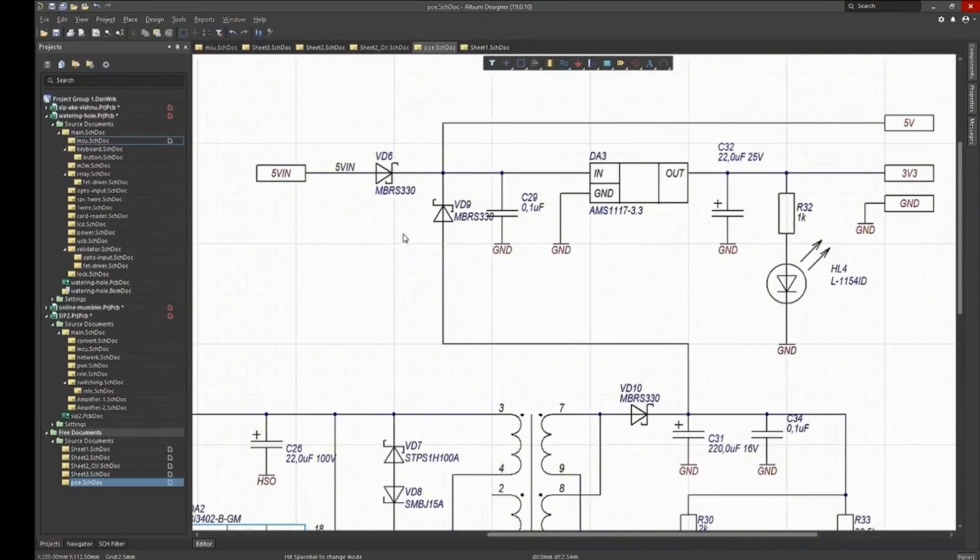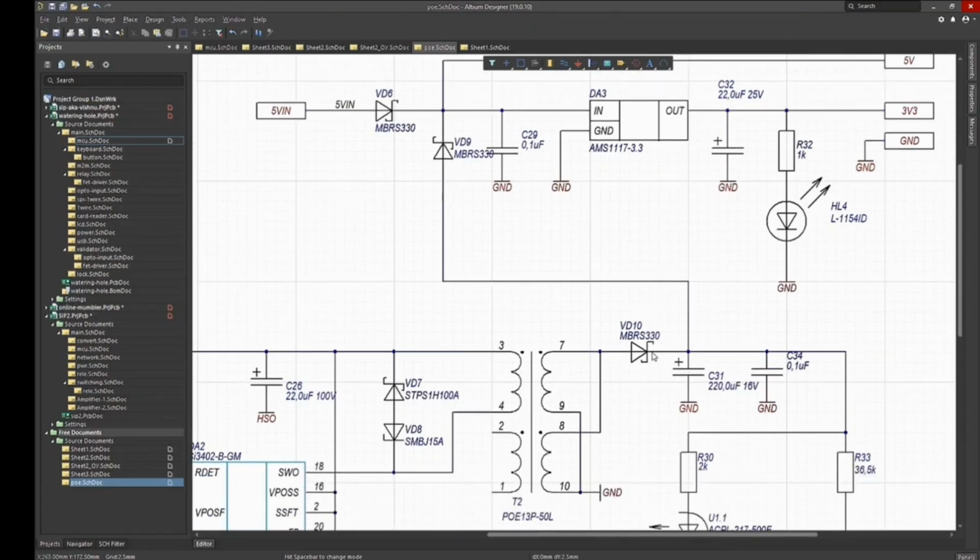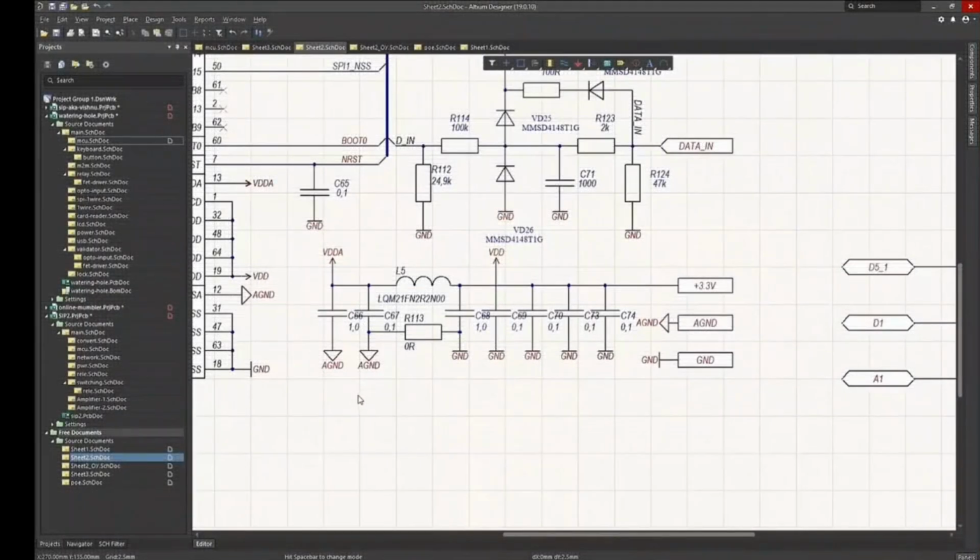The fifth mistake is not distinguishing analog and digital ground. Beginners often put everything in one pile, analog and digital, and then noise, jitter, ADC issues, unpredictable failures. Let's look at a separation scheme. Here, in principle, analog power is made from digital power and digital ground. The supply voltage is separated by an inductor, and the analog ground is connected through a 0-ohm resistor. In principle, you can also put an inductor or a ferrite bead here. This prevents interference from the digital ground from entering the analog ground.